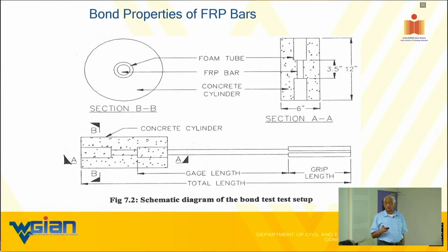So immediately I say my force divided by the contact area, pi d times the length, right? Or the bond stress, tau, is force divided by the area, pi d times the embedded length, right? That's what common sense says. Dead wrong.